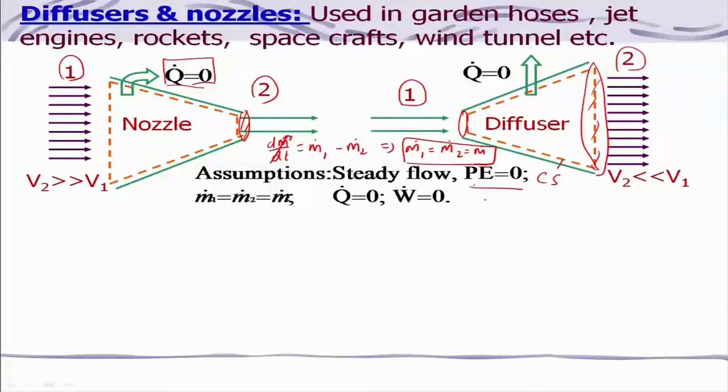That is nothing but your mass flow rate. If I consider, m dot 1 is equal to rho 1 A 1 V 1, right. That means rho 1 is the density, A 1 is the cross sectional area. This is your A 1, and this area is A 2, right. So, it is equal to rho 2 A 2 V 2.